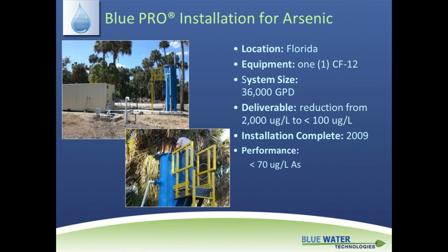So they would use arsenic baths, arsenic dips all over the place, and it just saturated the ground in this particular region. It's on tribal land, so the local Indian tribe was involved. The engineer in the state was involved to really clean up the groundwater, which is anywhere from 1 to 4 milligrams per liter of arsenic. So it's very high arsenic content. That's 1,000 to 4,000 micrograms per liter. Their target was really to get under 100.